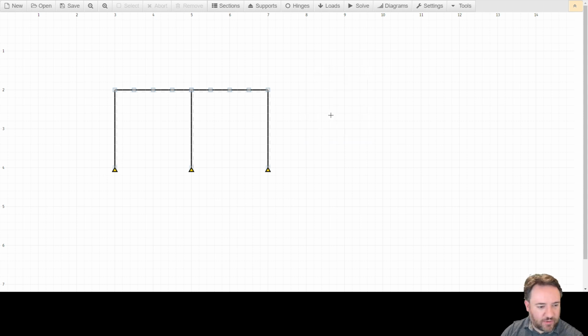What about now the dimensions of my frame? How do I get the right stiffness? This is an indeterminate structure, so the relative stiffness of all of these members is going to matter. Okay, so first thing I'm going to do is define my properties. Now for wood, I'm going to have to go to my wood design manual and figure out what my E is, for example. So if I go to my properties here, I haven't defined which E it is in my little example, but I'm just going to pick one. I'm going to say, okay, let's say the E for this is 6,000 MPa.